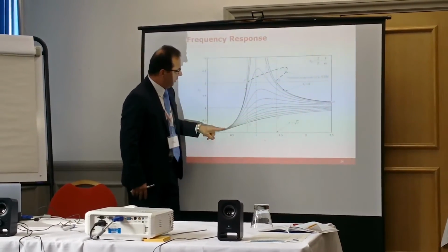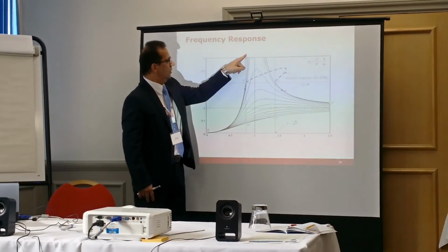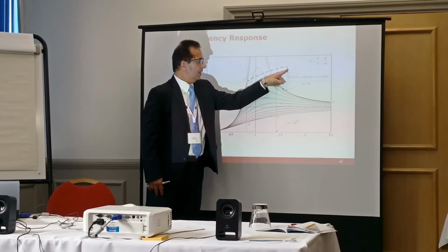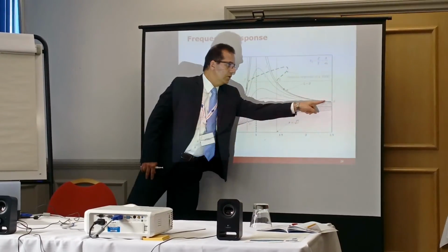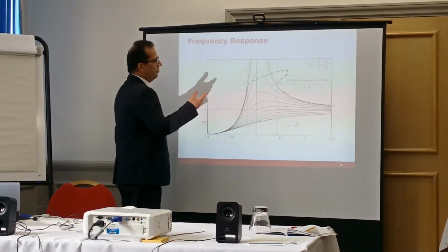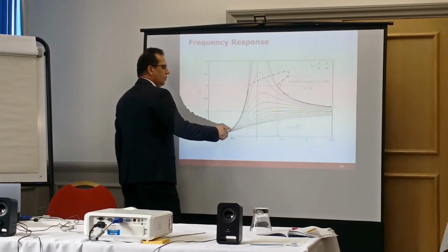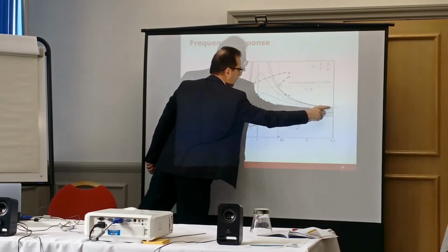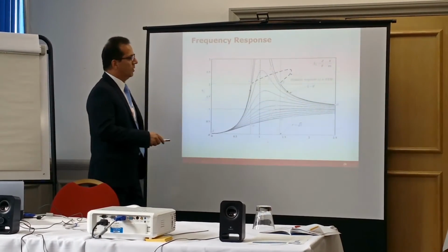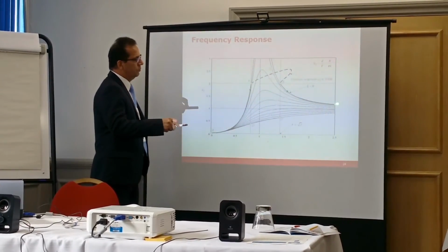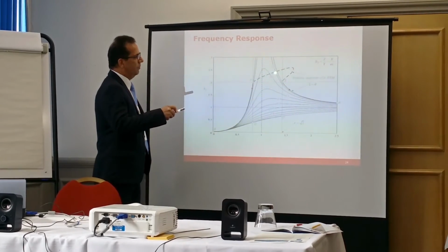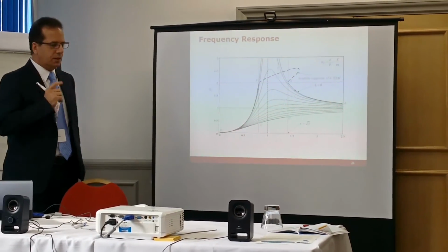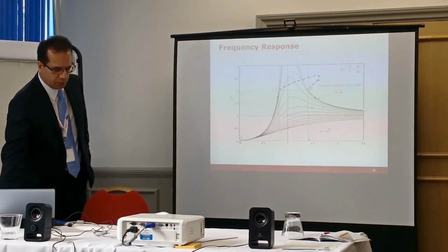Instead of following this curve, at this point we go to that curve, and then we come here and we continue. If you are familiar with nonlinear systems, you know it goes up to this point and then jumps down and follows, increasing the frequency. By decreasing the frequency, we move from A to B, jump up, follow this, and come back. Looks good. But there is something which we have to notice.